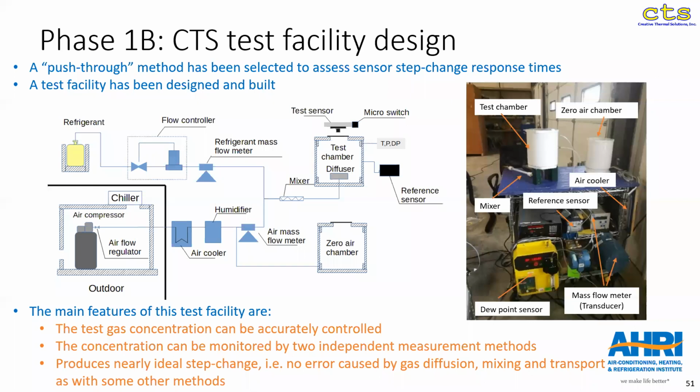How do we measure? With two different independent methods here. We have a reference sensor that is based on thermal conductivity principle, and that is more than one of the test sensors that is actually a higher quality kind of sensor with high accuracy. And of course, it's for lab measurements, not for mass production. The other independent measurement method is based on this refrigerant and airflow device, which we have validated also to give very accurate results. And so we have two independent measurements.